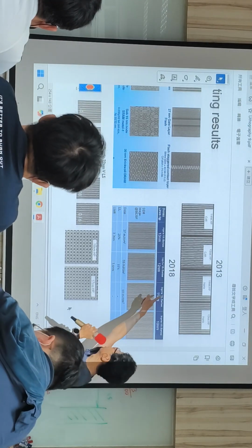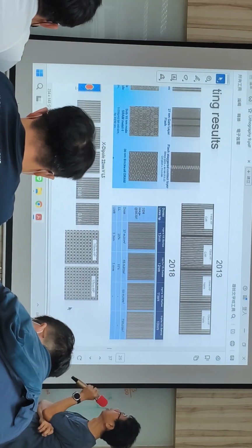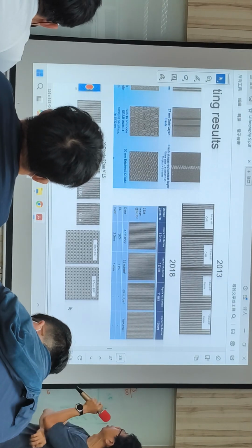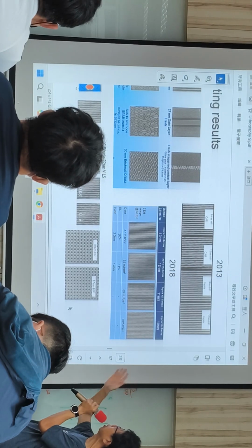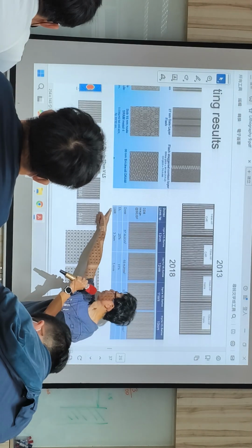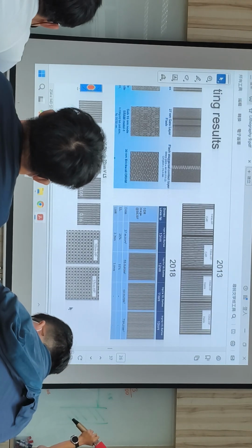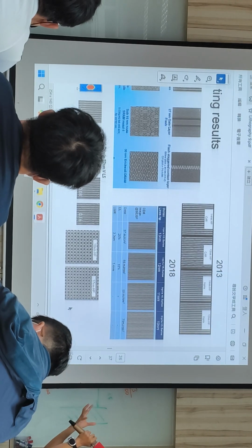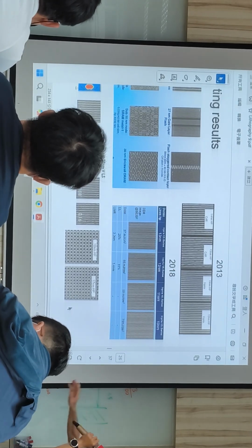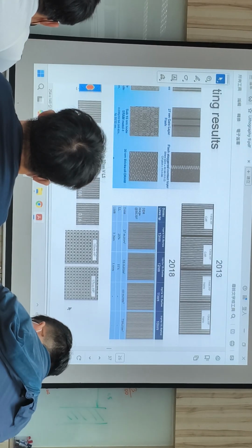So as I told you, CAR is basically a chemically amplified resist, and you can see the Inpria silicon containing resist has much less LWR. Okay? So that's why they wanted to show that. But in the end, people still tried to improve the photoresist and went back to CA, chemically amplified resist.